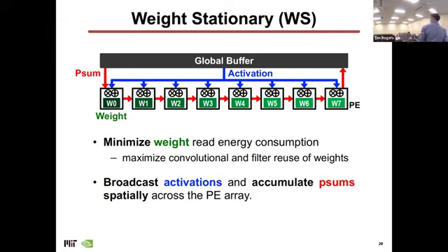It's pretty damn efficient, right? If you can time it all out correctly, there's no buffering, no storage in between. So you basically are always sending your output. Your MAC's always going to this network. Now in reality, if you want to send something on die, there's probably a buffer, a couple cycles of a pipeline or something, right? But you don't need a special instruction, it's only doing this instruction over and over and over. Does that make sense? So we're saying that the output is implicitly always sent. Correct. There's never a reason for me to do anything with my output except send it to the next element.